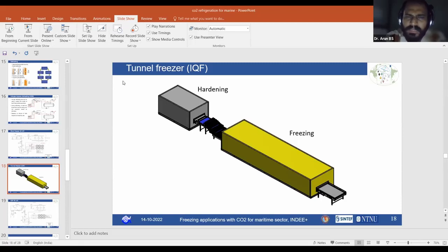For the standstill pressure, there are only two methods that are currently used. One method is to have a backup system to cool this receiver to maintain our standstill pressure. The next one is to design our full system for the higher pressure, higher bar. We can't have any other arrangement because it practically doesn't make sense. Okay, sir. I have read somewhere in a journal, that's why I'm asking. Maybe some new research is going on, but we didn't explore that much.